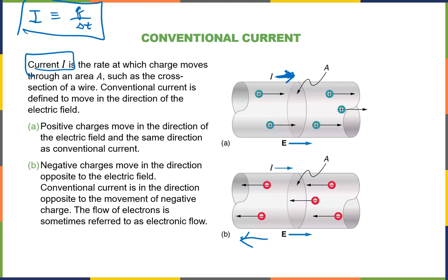The signal travels at the speed of light in whatever the insulation is. And so the speed of light in polyurethane is about 2/3 the speed of light in vacuum. So that's how fast electrical signals go through most insulated wires. If you have uninsulated wires, then it goes at the speed of light, because it's going actually on the outside and dragging electrons inside.